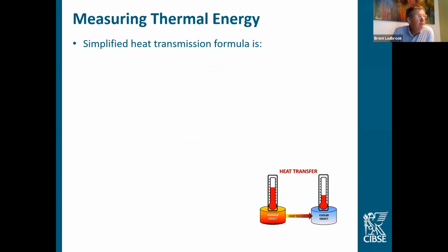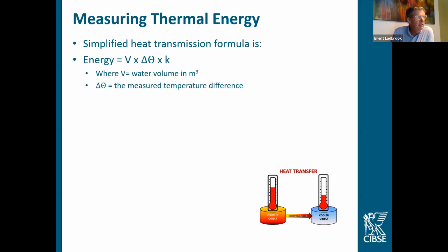We have our flow sensor, and the calculator is doing this calculation fairly constantly. We're measuring the water volume in cubic meters. A lot of engineers here will specify flow rates in liters per second. Hydraulics engineers work that way, but the standards are all in cubic meters and cubic meters per hour. So the factor is 3.6. One litre per second would be 3.6 cubic meters per hour, and meters are all sized that way for flow rate.